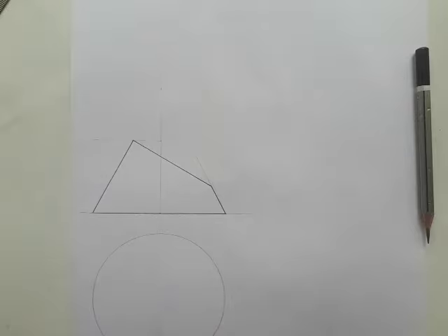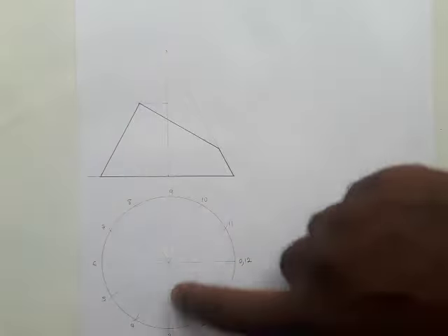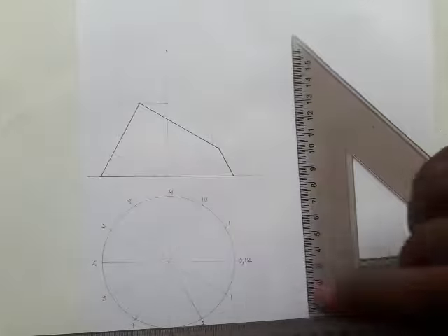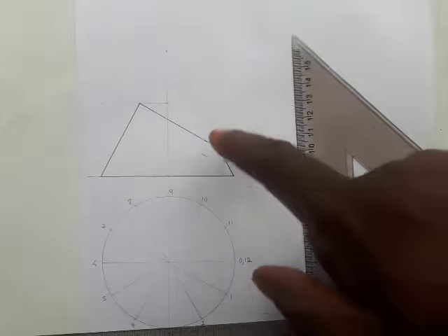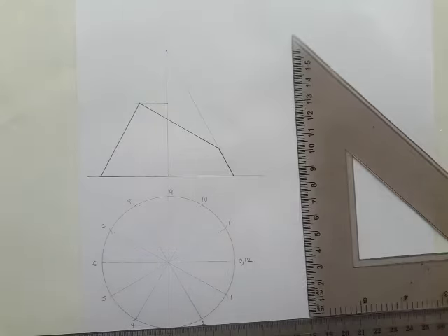So that's the plan with a thick line or thick arcs. All right, so divide the plan into 12 equal parts. So there you have it, divided into 12. Now you could check other videos on special curve I did previously to learn how to divide the circle into 12 equal parts if you don't know how to. So the next thing I'm going to do now is to draw lines. This vertical line, I'm going to transfer it using my ruler and set square. Now, once again, if you've not seen the video on how to develop a cylinder, I think you should go see that video, because I'm going to skip some parts.